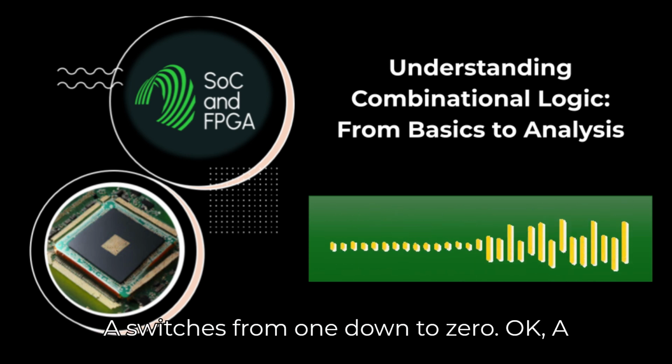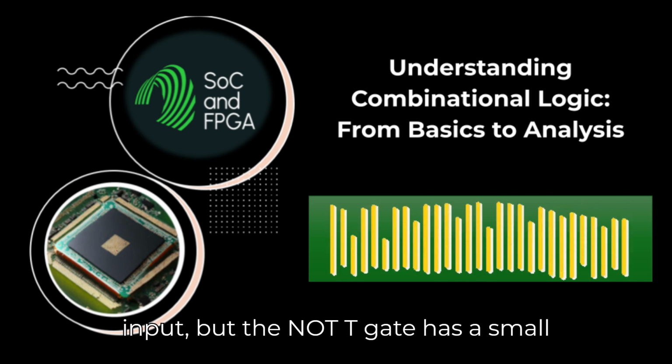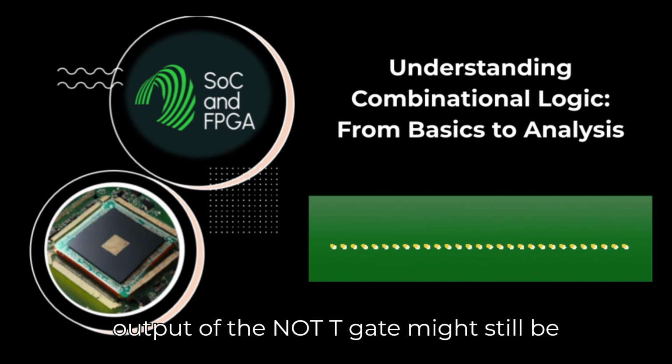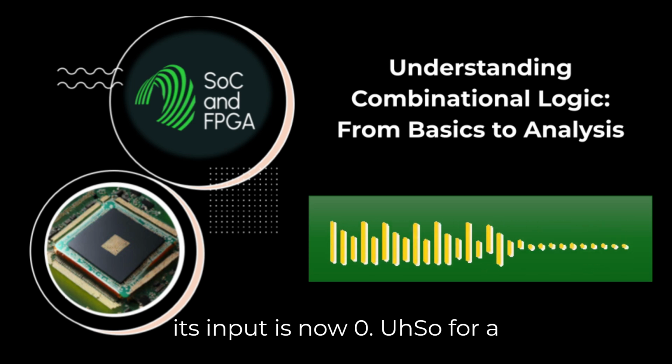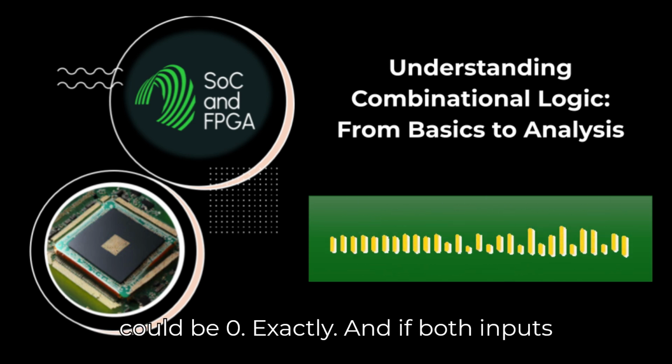Now, imagine A switches from 1 down to 0. Okay. A itself goes to 0 immediately at the OR gate input. But the NOT gate has a small propagation delay. So for a tiny moment, the output of the NOT gate might still be 0, the old value of A prime, even though its input is now 0. So for a split second, both inputs to the OR gate could be 0.